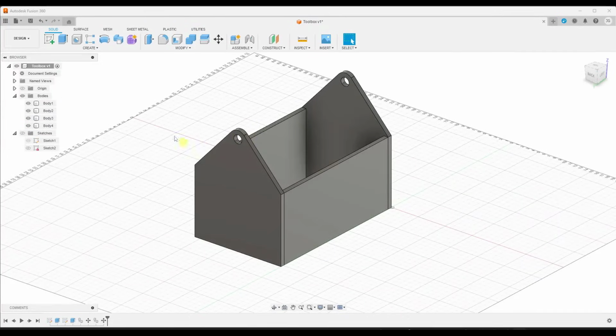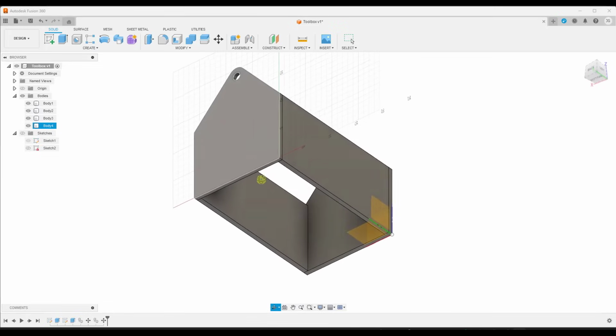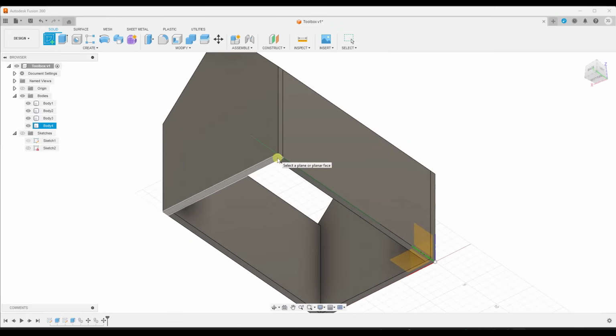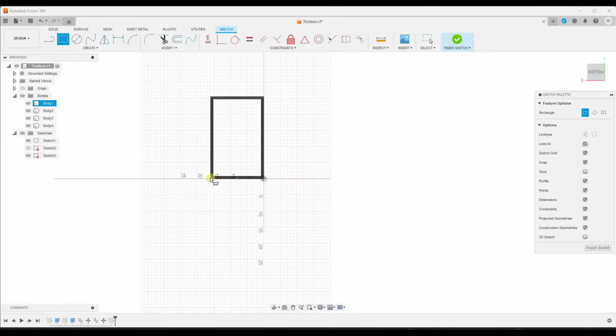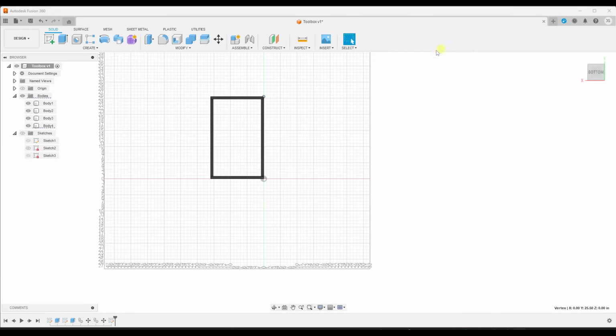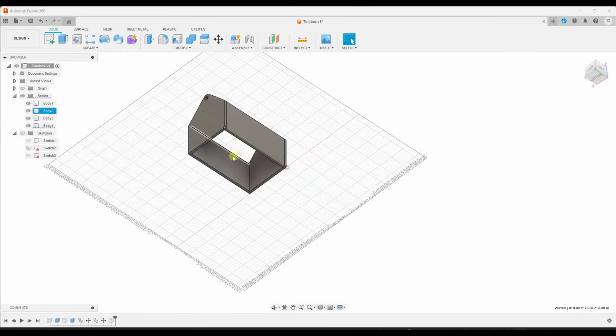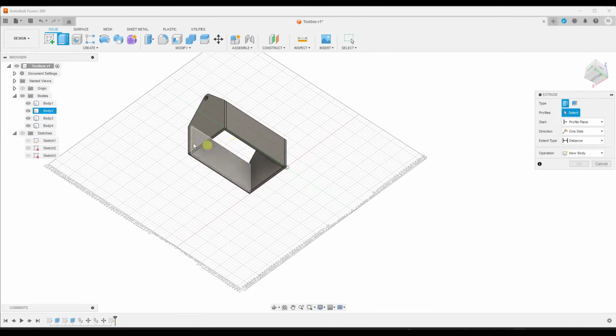And so remember, we're going to do this by creating a sketch. So I'm going to click on create sketch. In this case, I'm going to rotate down and pick one of these base planes right here. And in this case, I'm just going to tap the R key to activate the rectangle tool, and I'm going to click on this object and finish the sketch. So now if I orbit out of here, I can take that sketch and notice how that sketch is toggled off.